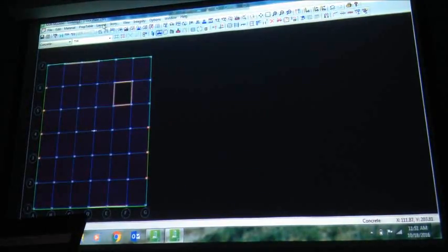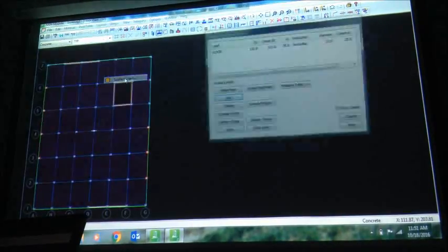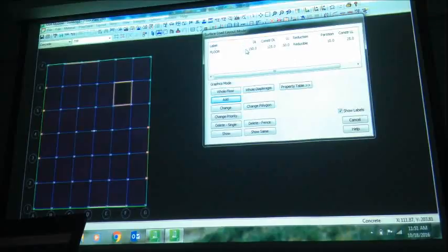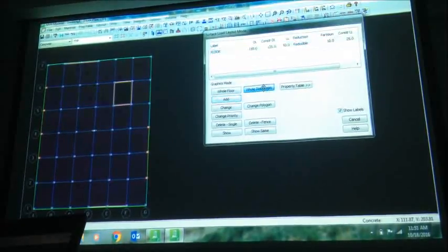So now I have defined the loads, but I have to place them. So go to loads, surface load, select this surface load and say whole diaphragm. The color change means it's already applied. Did you follow me? Okay.